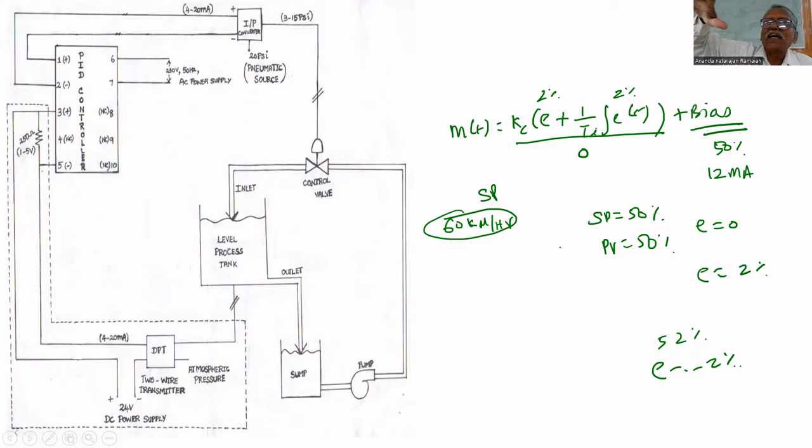So, there is a non-linear relation between speed and acceleration. That's why you cannot directly put the PID controller in action like that. To understand, I'm telling this example. You have to bring the speed to 900 kilometers per hour, then you put it in the PID controller, and it will take care. At 900 kilometers per hour, 50% is the power pumping, that's why it is moving at that speed. Any change, it will adjust about 50%.